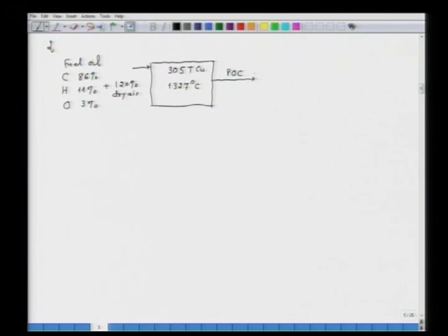they enter into a waste heat boiler. Now, recall, waste heat boiler is also a typical device for recovery of the heat. It is used to produce superheated steam, and ultimately the products of combustion discharge at 316 degrees Celsius.